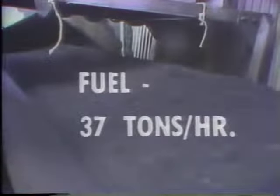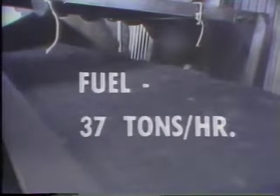The fuel requirement for this unit, producing 100 megawatts, is around 37 tons of coal per hour. To burn 37 tons of coal per hour, the operator has to mix it with about 1.5 million pounds of combustion air per hour.